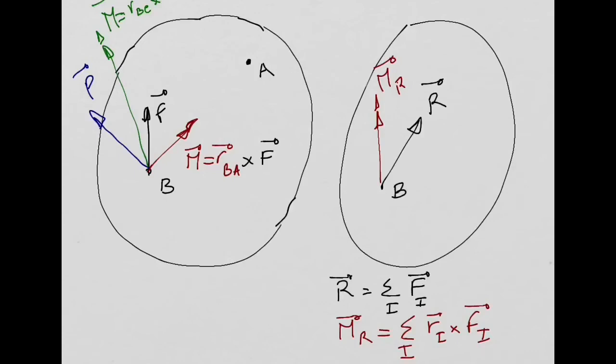In this case, it is going to be equal to the summation of the moment we have in green with the moment we have in red. So I add all these vectors together and I have a resultant for the moments as well. And then I will have this equivalent system at the right-hand side. You can see we have everything, forces and moments, concentrated in one single point of our structure. And what are we going to do now to study the equilibrium? Well, I'm going to say the resultant of the forces needs to be equal to 0 to be in equilibrium.